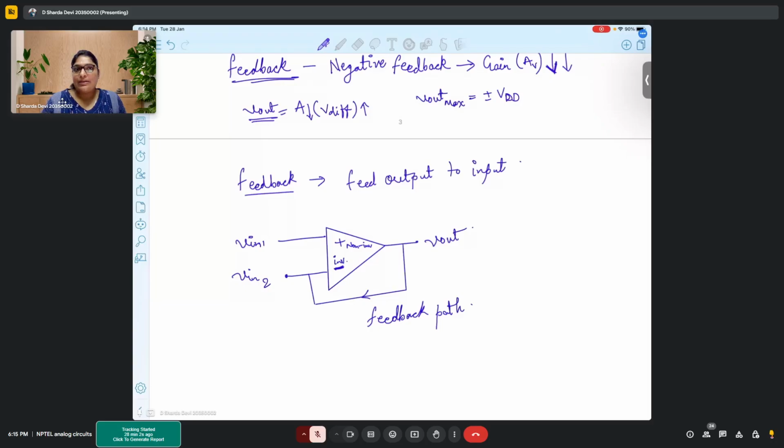Or in mathematical terms, your output will have a negative value with gain times the input. Inverting, from the physical significance, means a 180-degree phase shift in the signal, and mathematically you will find a negation in your output. So whatever signal you give in input, your output will have a negative value.